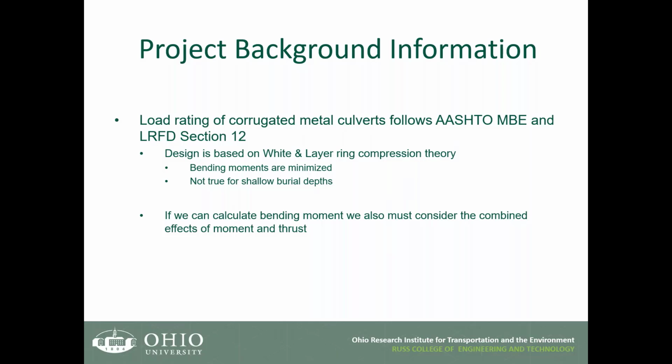Well, for shallow burials, that's just not true. For deep, that is relatively true. But for shallow, it's not true at all. And as Dr. Sargan talked about, actually the moment starts to dominate the response much more than what thrust does. So if we can get to a point where we can calculate the bending moment, we now, as Dr. Sargan talked about, have to consider the combined effects of moment and thrust.